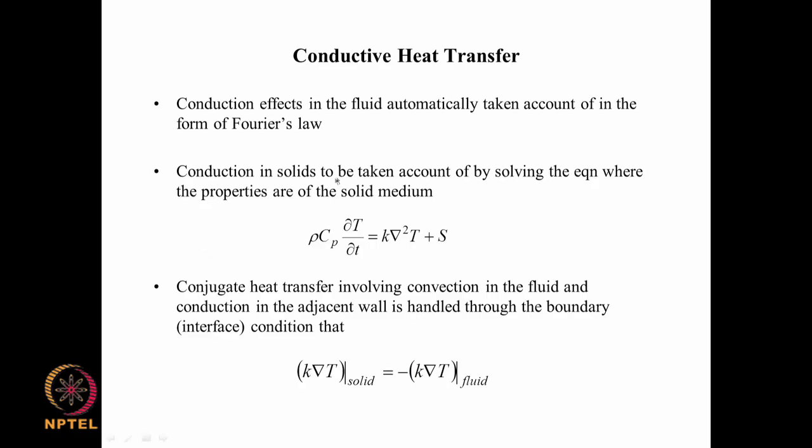Conduction in solids should be taken into account, okay. Conduction effects in the fluid are automatically taken into account in the form of Fourier's law, which is applied to evaluate the conductive heat transfer within the fluid continuum. Now, if we are talking about the solid, for example, we have a fluid here and then a solid in between and then a fluid here, then there can be heat transfer from this hot fluid into the cold fluid through this